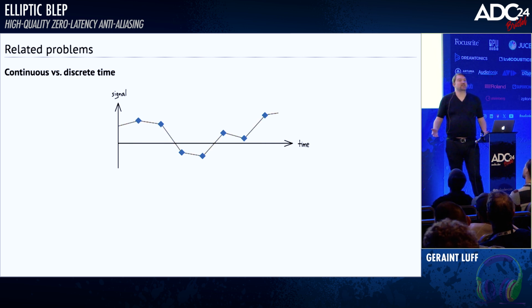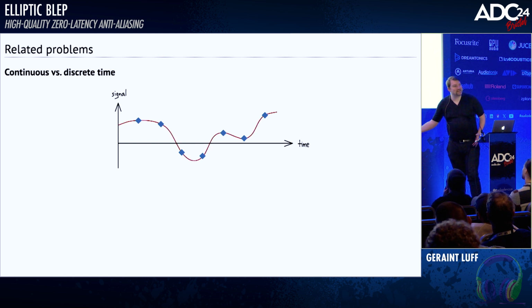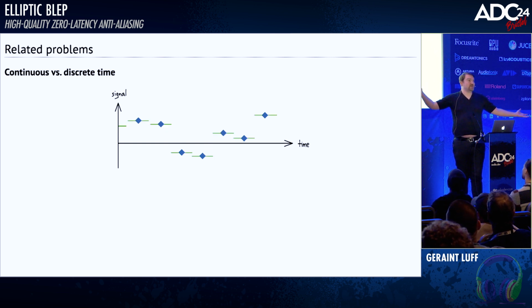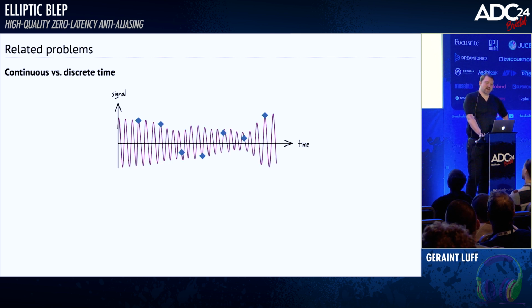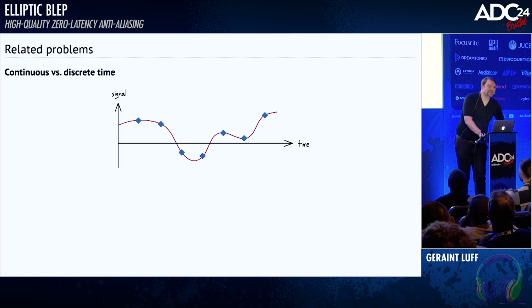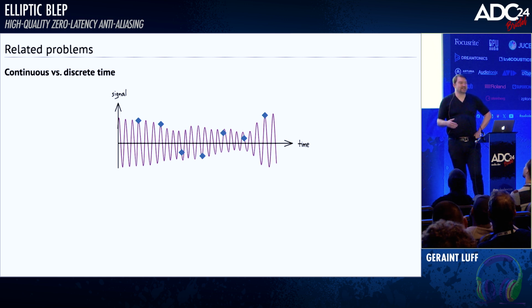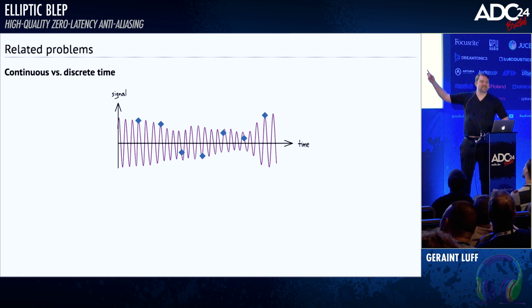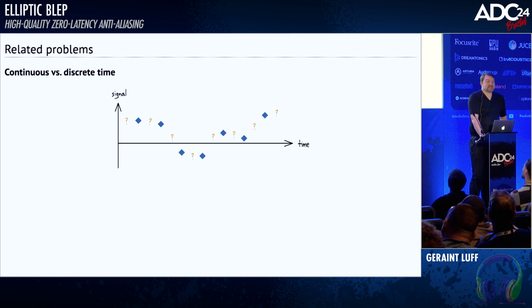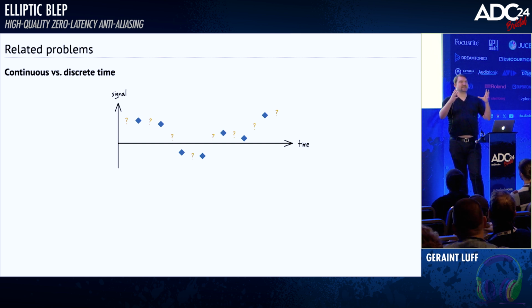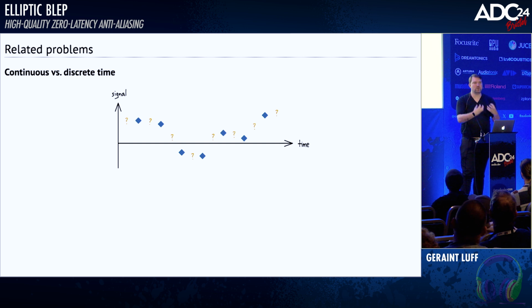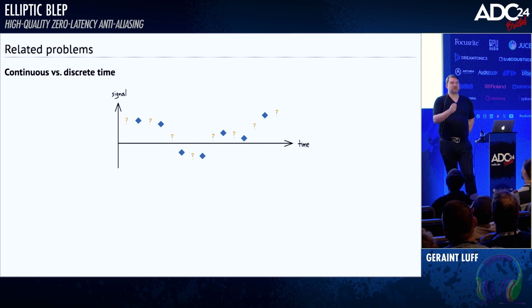And I don't know, maybe you're linearly interpolating between them. Maybe there's a nicer, smoother interpolation. Maybe you're just using the nearest sample. And some of you might say, yeah, well, sinc curves, obviously, is the correct move here. That's not necessarily true, actually. When you get into spectral processing with STFT subbands or even software-defined radio, you'll find that sometimes these sampled signals are representing frequencies way higher than the sample rate. But the point is, you have to know what is happening in between your samples and decide how these samples extrapolate to continuous time, and then make sure that the calculations you're doing or the interpretation you're using match.